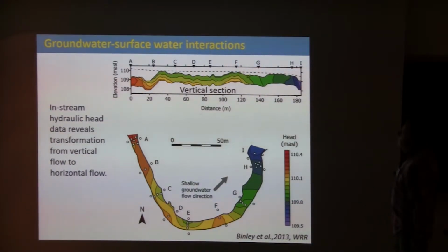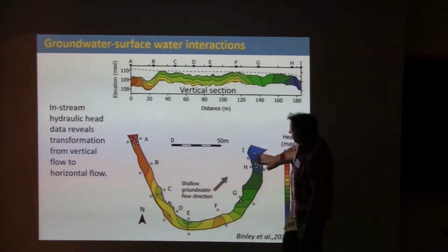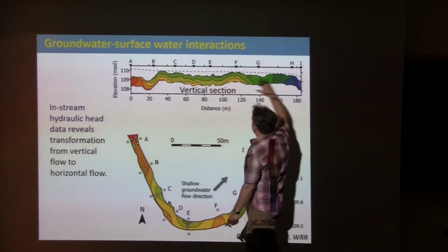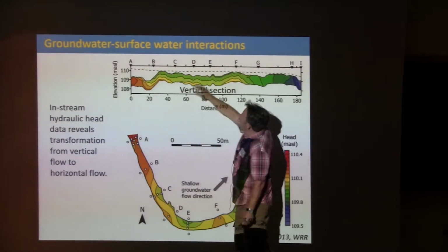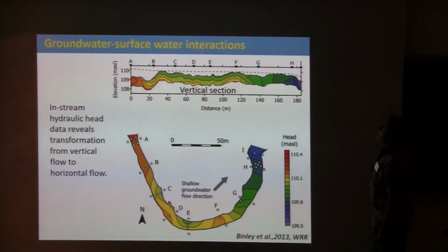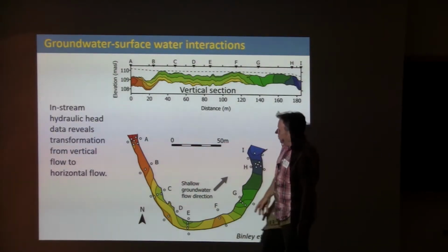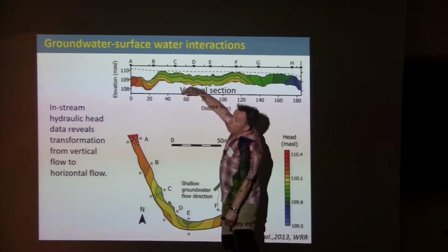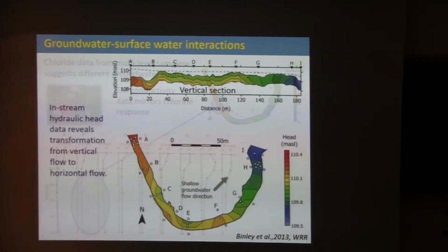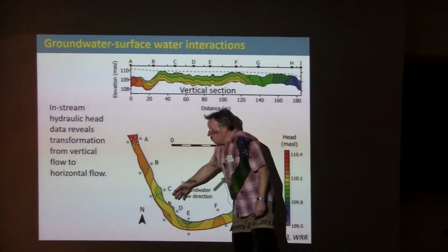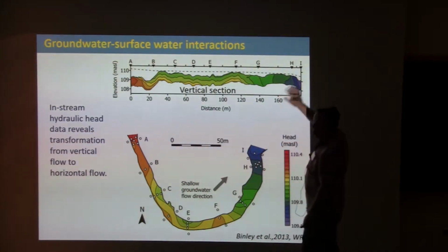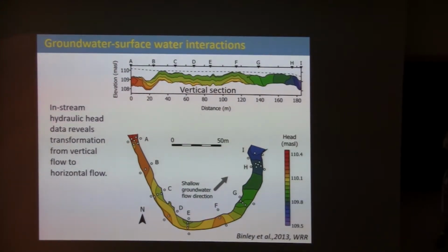We had piezometers, and they're multi-level piezometers, so we could look at hydraulic head variation in the vertical. It's an interpolated map based on our piezometer clusters at different points. And then here's a map of our hydraulic head data. You can see on here that we have contrast between the upstream and the downstream. And you'll also see we've got very significant vertical gradients in this upstream part. And this all fits together with the regional groundwater flow movement, which is in this direction, driven by a major river course somewhere up in the northeast of the site.